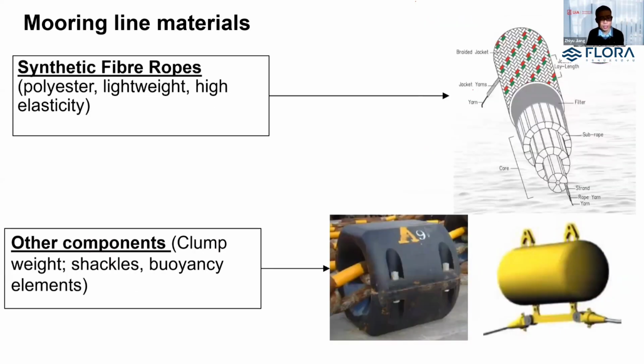Steel wire ropes are also relatively cheap compared to chain because they are much lighter. But in recent years, synthetic fiber ropes have been increasingly applied in offshore wind projects because these ropes are very, very lightweight and even more cost-effective than traditional material. But the challenge is the material property uncertainty related to such material. So significant testing is required before we can put them into use. There are a few ongoing knowledge building projects in Norway related to fiber ropes. This is a very important and interesting development for mooring design.